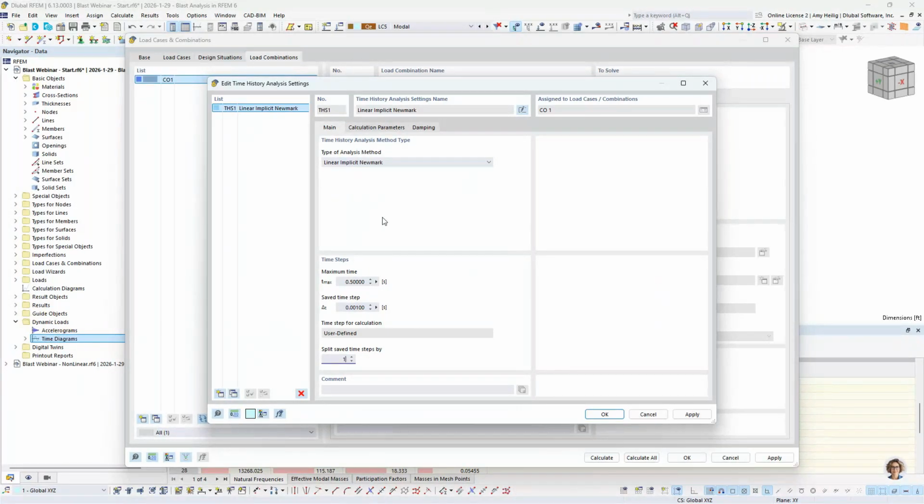If they do, then you need to continue reducing these time steps so that eventually we see the same result output between the time steps themselves. And this is really a balance. We don't want to be reducing the time steps so small that the calculation is taking too long. But if you set it to something too large, then you're not going to get accurate results. So again, carrying out that time step study will be very beneficial.